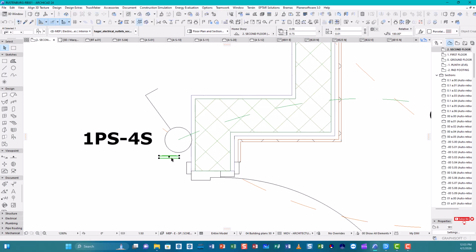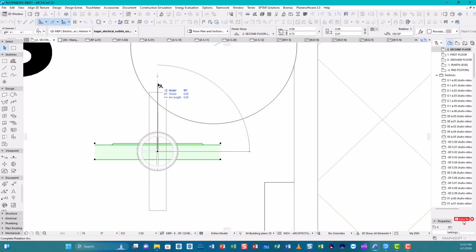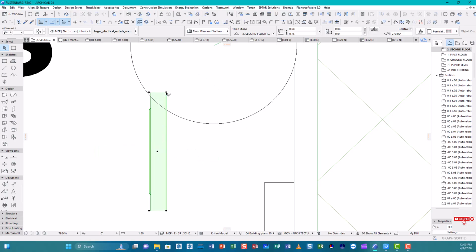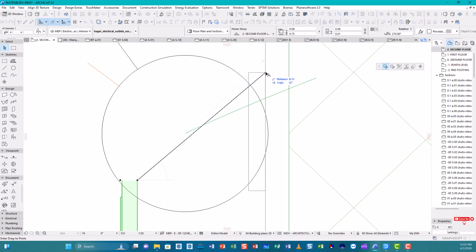If I zoom in here, you can see that this side is the front side, and where there's no extra geometry constitutes the back. So I'm gonna press Control E to rotate the element. Click once on this side, rotate it to the other side, and click again for the second time. Once the element is rotated, I'm just gonna click on it and put it at the exact position where I want it to be. I'll join it a little to this side, put it right at the center, because I want it to be centered to the symbol there.